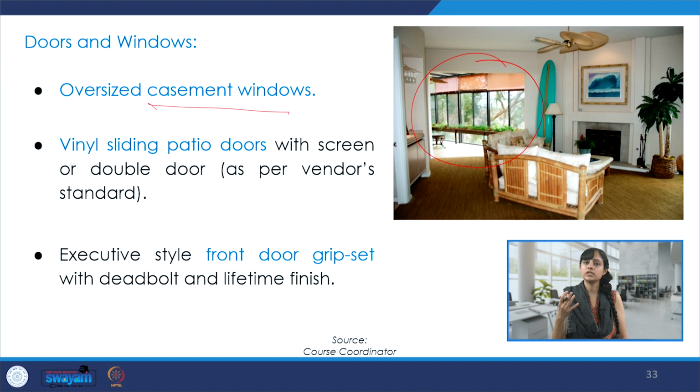So when we see interior design drawings and representation techniques, there we will probably discuss some of these. It is like, God is in the details. The drawings have to be really elaborate with each little detail, all inventories, all door and window schedules. Every kind of small to big detail has to be given along with the specification, material detail, dimension, everything. And in the case of tiles, we will see whether it's a herringbone pattern or what it is. All those things we have to put together when we are producing the interior architecture drawings.